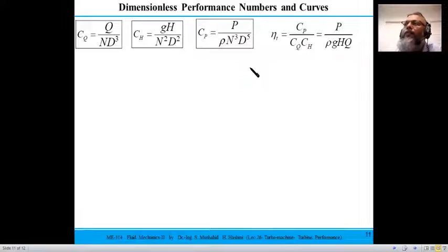And so you can easily work out the formula for the efficiency of the turbine, which is opposite in that case, because in a turbine the desired output is the shaft power, and for that desired output you need to give power to the fluid. So your flow and head coefficients would be in the denominator. For a pump the formula would be opposite: power transferred to the fluid divided by what is input, where the desired shaft power is in the denominator. Swapping numerator and denominator, you would have the same expression as for pumps.